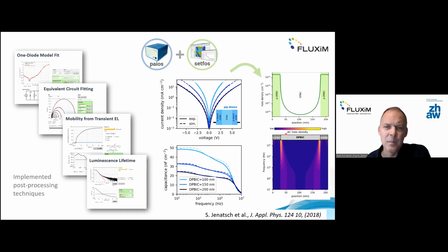And corresponding to this frequency sweep, you get the frequency dependent charge oscillation in the cross-section of the device. This allows you to understand why you have a low frequency capacitance rise. That basically means your oscillation of charge carriers penetrates more deeply into the device compared to the more medium frequency range here.